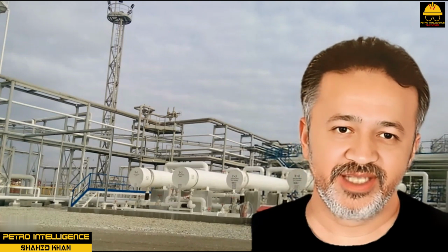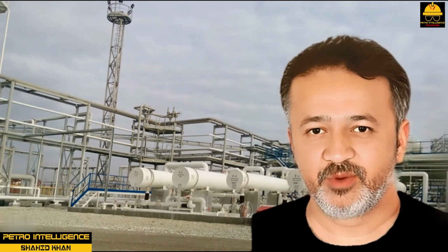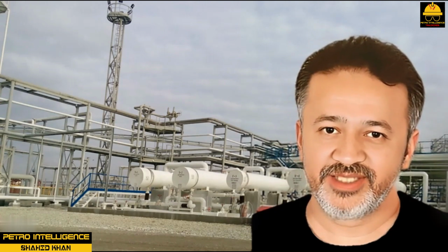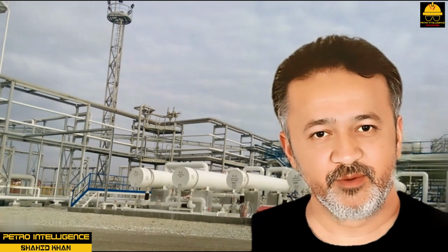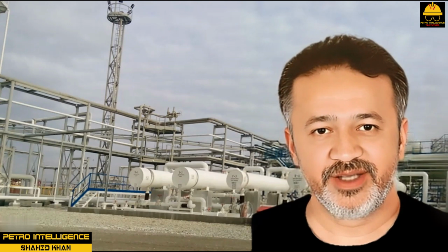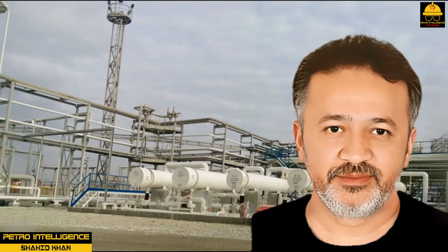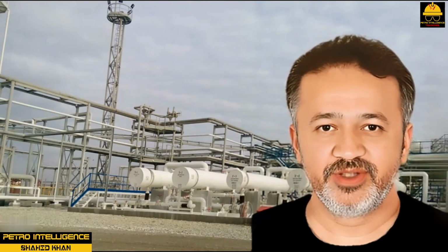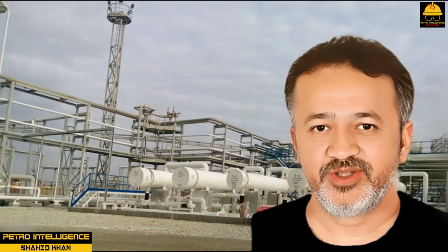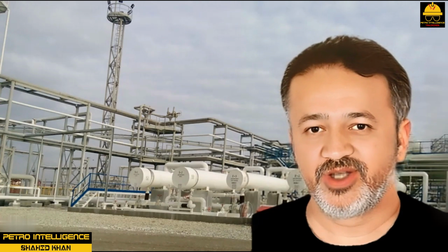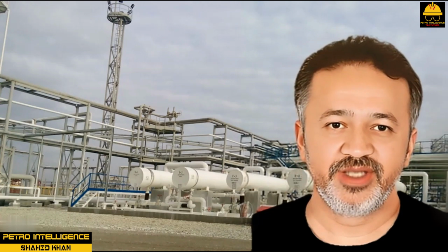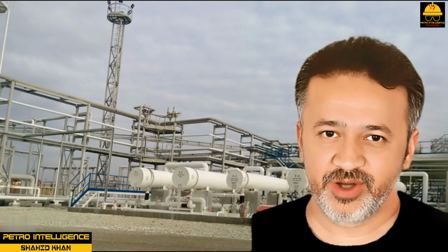The shell and tube heat exchanger is the most common in the process industry. Shell and tube heat exchangers are designed to handle high flow rates in continuous operations. Reboilers are used to maintain heat balance in distillation columns. Kettle reboilers and thermosiphon reboilers are the types most often used. Condensers are typically shell and tube heat exchangers often used in distillation columns to condense hot vapors into liquid.